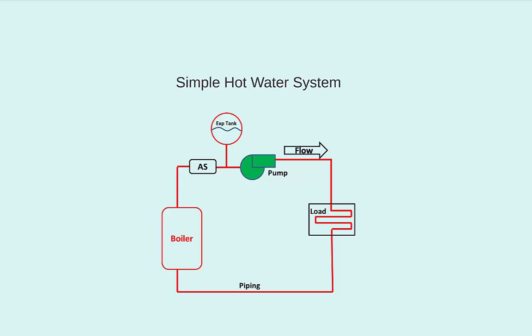That is the same cold water that runs out of bathroom faucets, and it is typically around 50 to 60 degrees Fahrenheit. When we fire up the boiler, we are often running at temperatures on the order of 200 degrees Fahrenheit. As water is heated up, it expands. It doesn't expand a ton, but enough that if we didn't have a place for it to expand into, that is the expansion tank, it may burst some pipes.